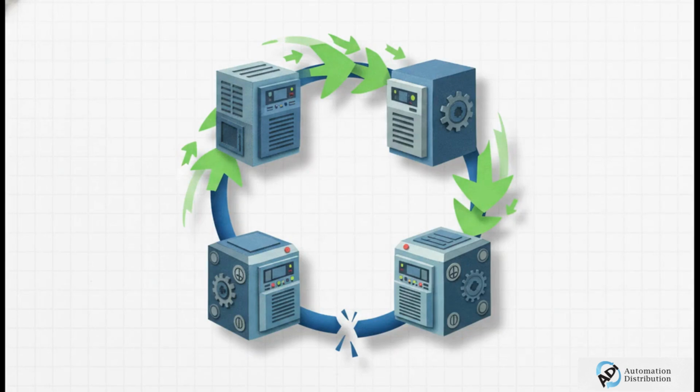All right, first up, if you crack open a panel here in North America and you spot a Rockwell PLC, EtherNet/IP is almost always your path of least resistance. It applies the common industrial protocol directly over standard Ethernet. The entire I/O tree, the device catalog which uses those EDS files, the diagnostics, it's all natively built right around it. And hey, here's a pro tip for you. If you see devices wired in a loop without a central managed switch, you're probably looking at DLR, or device-level ring. It's a specific setup that lets the network survive a single cable break, and it is a massive dead giveaway that you're deep in EtherNet/IP territory.